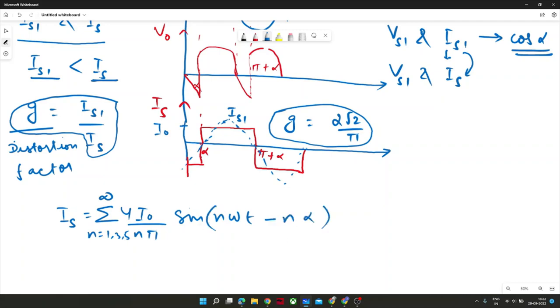Why am I writing this expression? If there is any square waveform, I am just telling you a shortcut. You can either derive it from the concept of Fourier series. But in power electronics, if you know the Fourier series of one or two kinds of waveform, you will easily get through all types of problems because you will majorly see a square wave, because the work of power electronics is to provide a sinusoidal thing, but that fails in that purpose.